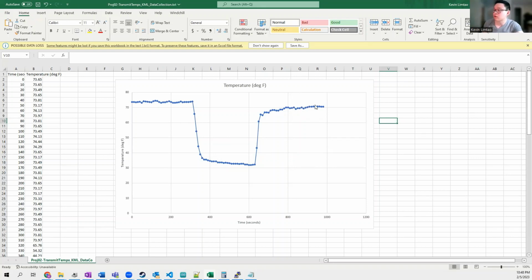If I left this running for a little bit longer, it might have stabilized back out to the baseline temperatures that I was seeing early on. My hardware setup doesn't have a ton of thermal mass, but the components were still cool to the touch a little bit. The thermistor bead itself was probably not a big thermal mass at all, but could still contribute as to why we didn't hit very close to 73 degrees, which is where we're starting at the thermal baseline.